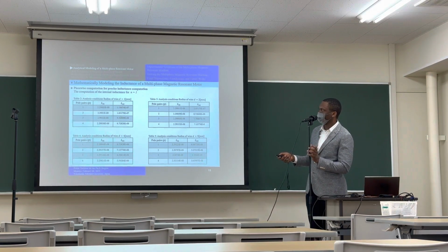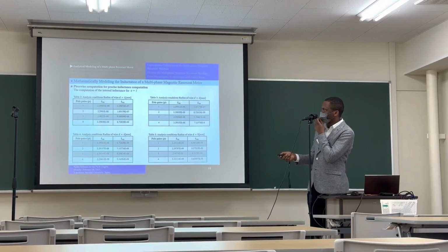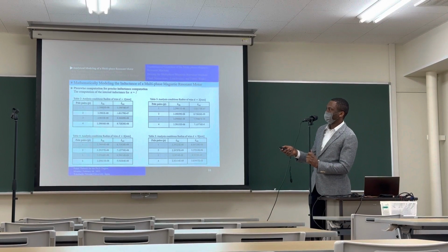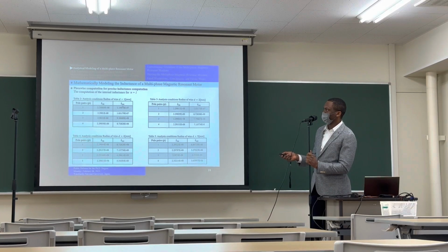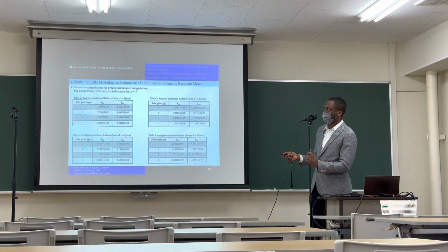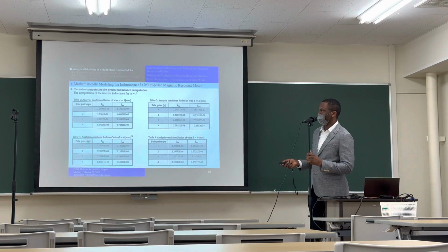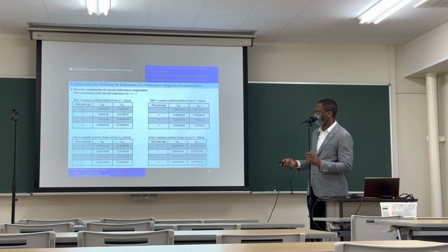So we can use the most significant inductance to describe the inductance of the machine, depending on the kind of wire that we use. If we were to use very small wire for one pole pair, you realize that the internal inductance is very small, it's insignificant. So we can just calculate the inductance due to the external field, and get the total inductance of the machine. This kind of analysis permits us to understand how we can easily calculate the inductance based on how the machine is wired.